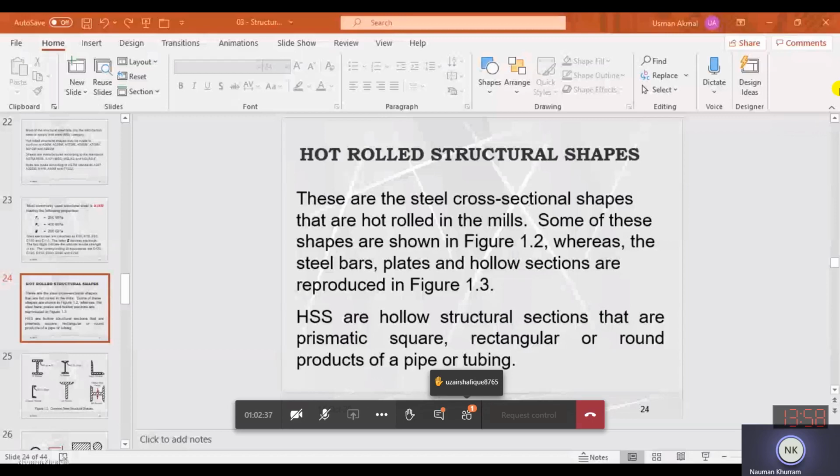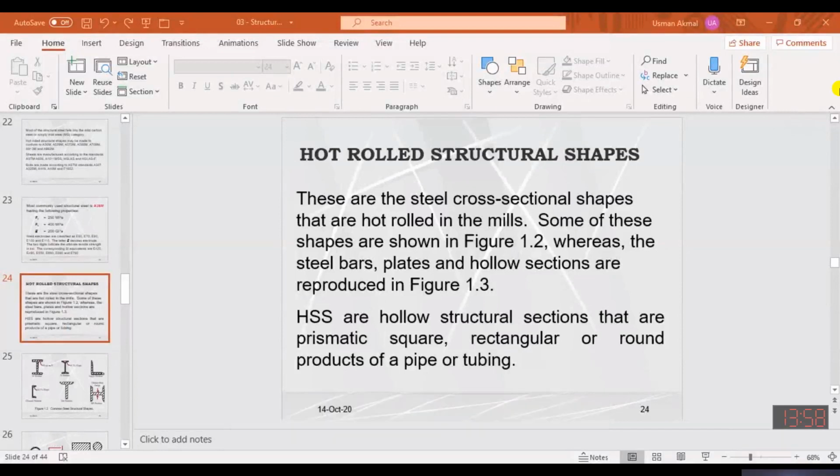Sir, like in A36 we had an M written in front, and if nothing is written after it, then it is actually mild. If it is not written, there is no problem, because in civil engineering projects mostly we have to use mild steel because we need large ductility. You understand me? So even if M is not mentioned, it is understood that in most of the cases it will be mild.